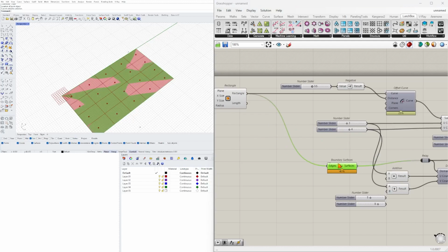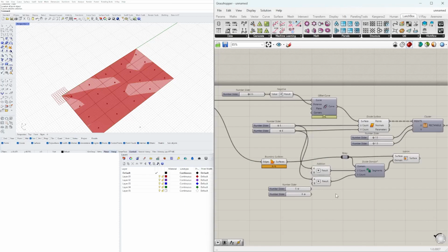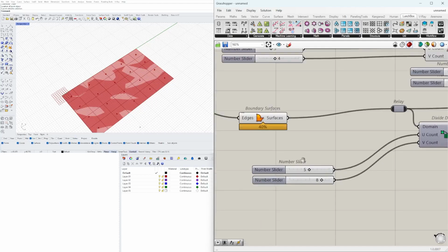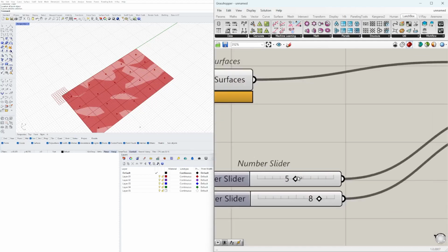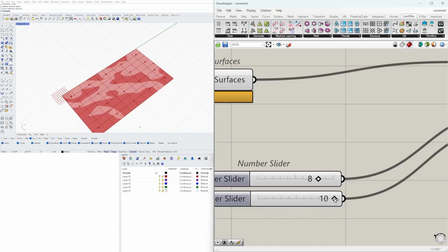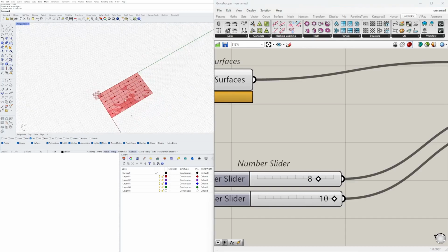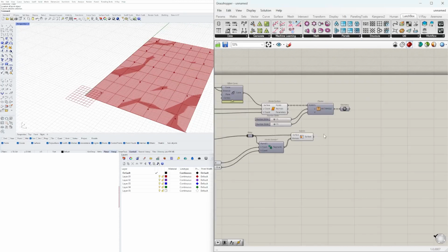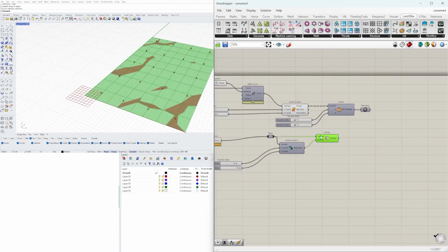So this is how we can tie it to those, but we actually can't tie it to that because the column doesn't even land in the center there. So I would say create your own waffle slab pattern here, depending on subdivision. So it could be twice as much as that. It can be whatever pattern here. And it will be subtracted from where the columns are.